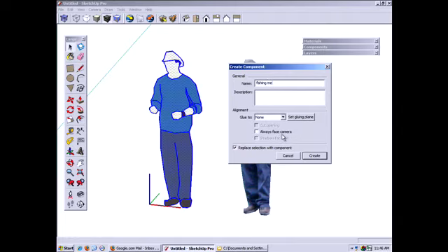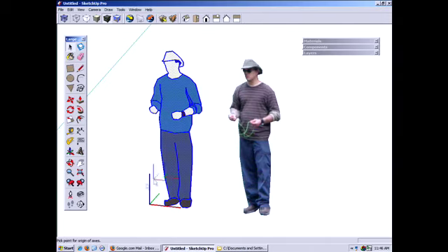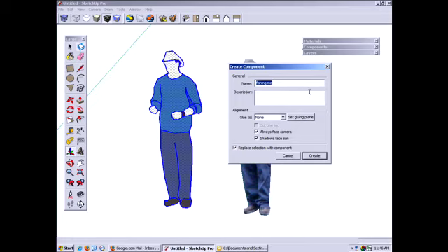Always face camera is an option. It's not checked, but if we check it, then now we're going to have a face me component. The important thing here is to change the axis so that it faces us like we want it to. And let me show you how we don't want it to work. By default, the axis is over here at whatever the farthest side of your geometry is, on the left side. I'm going to set this gluing plane even farther over here as an example of how this should not work.